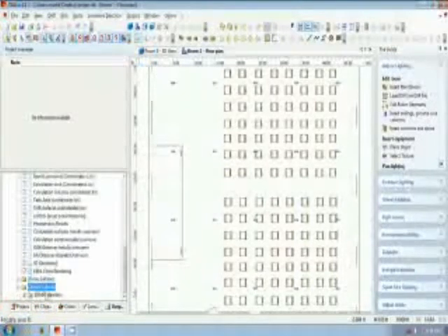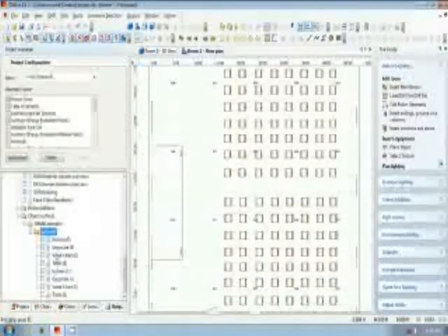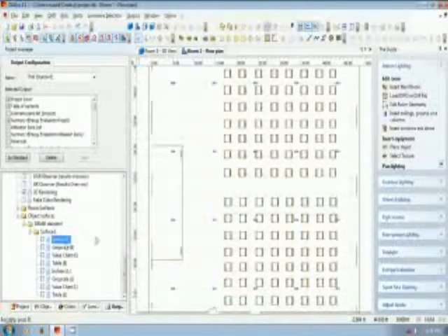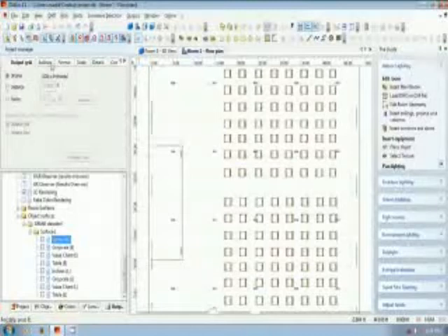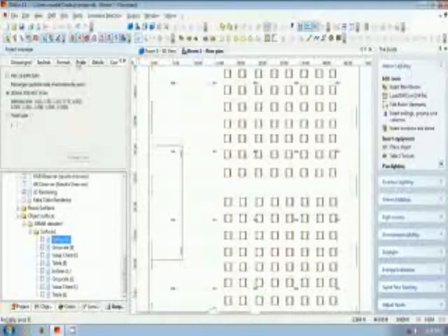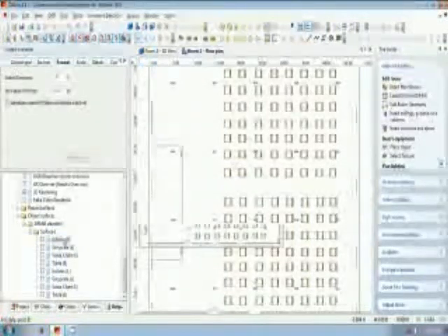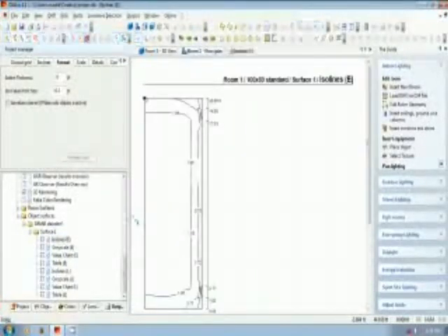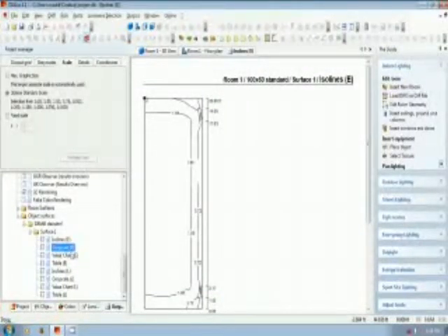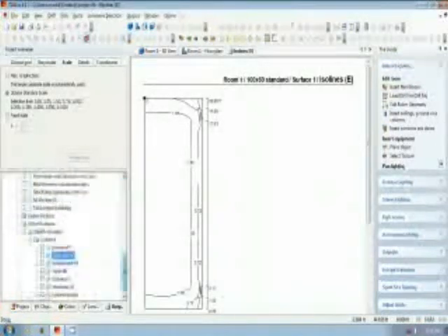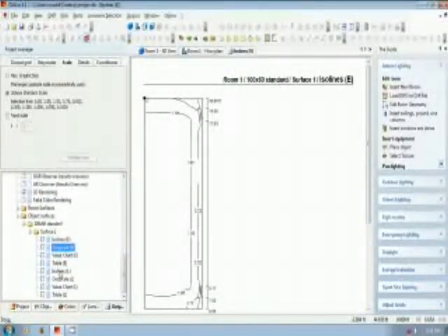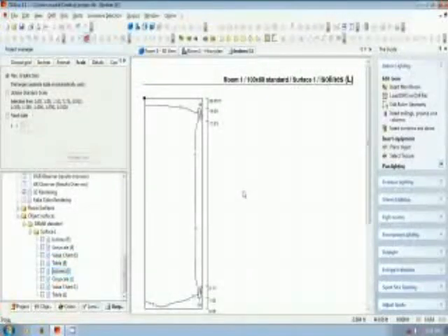This is discussed later, but you have to also change the surface, or you can edit the lux at a particular place. For example, let's take surface 1, the table top side surface. So you can see the isolines at that surface in this sphere. Now there is E for illumination and L for luminous intensity, which give values in foot candles